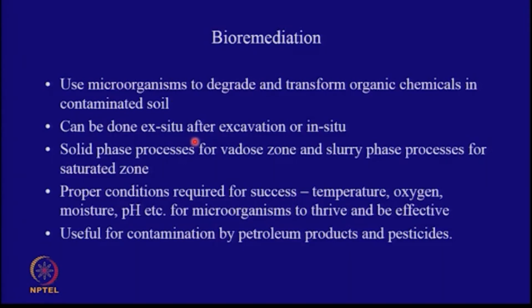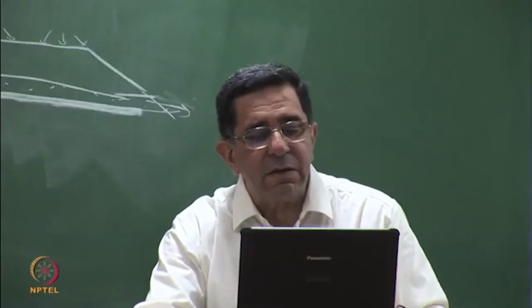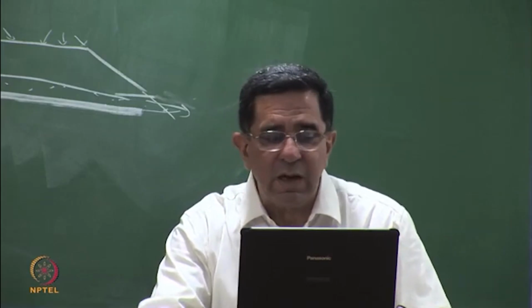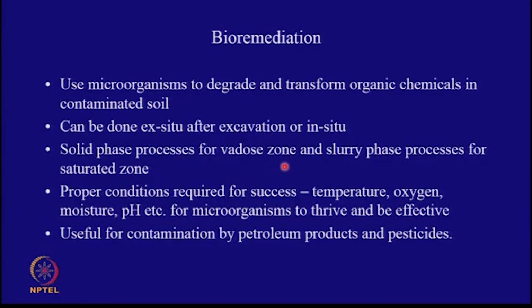However, at some locations bioremediation has been done in situ as well. And there you need very hardy microorganisms, but you are able to do it in situ as well. The processes when you are dealing with vadose zone are separate, and the processes when you are dealing with the saturated zone are separate. Please remember, these are different biological processes.